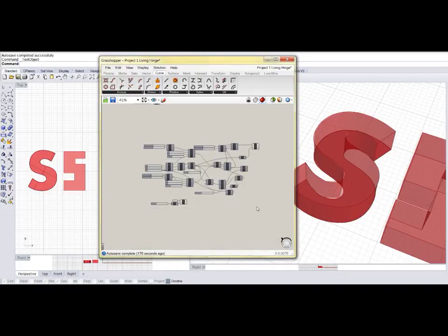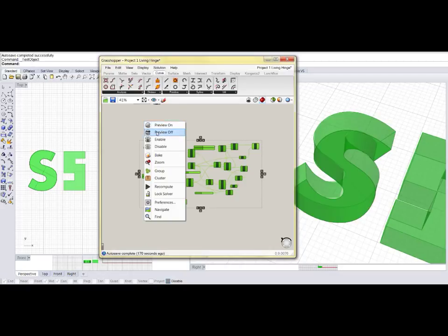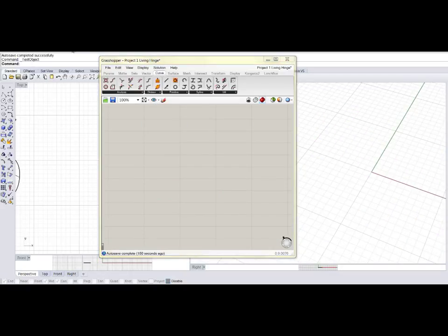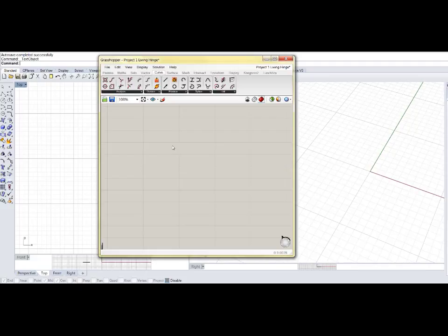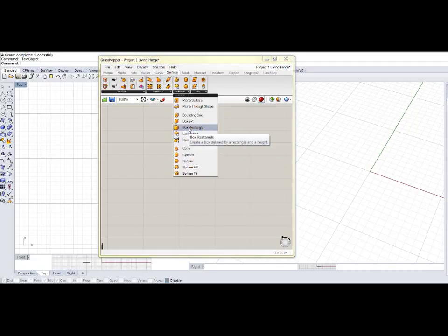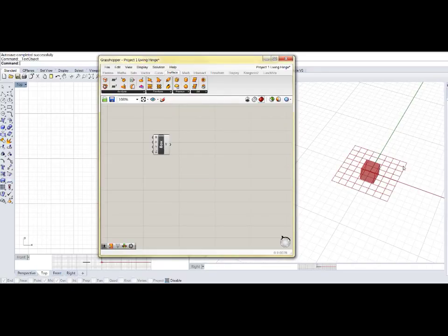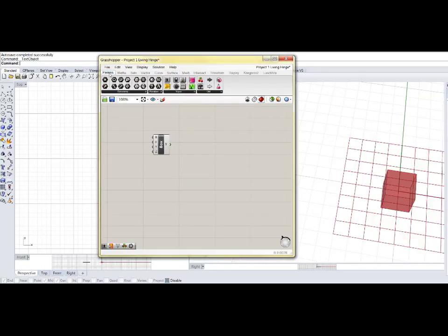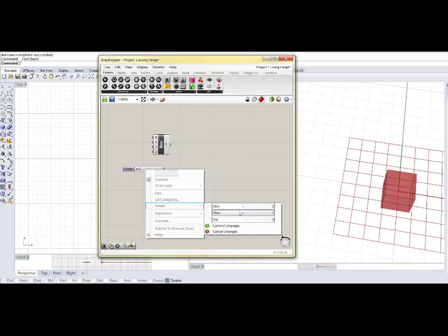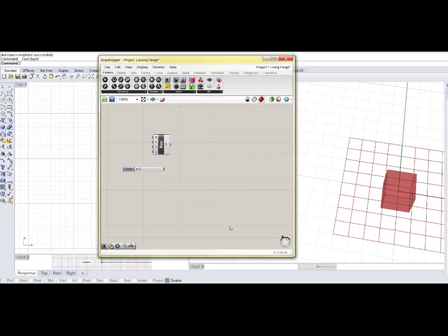Okay, so let's start with a blank canvas. Imagine we have a 3D block which we will sculpt and remove chunks out of, so it would result in a 3D letter S. Let's go to Surface, Primitive. Let's use a center box. We'll use the parametric slider, so go to Parameters tab, Input, Number slider. Slider type integers. Let's change this value to maximum 20. Commit.